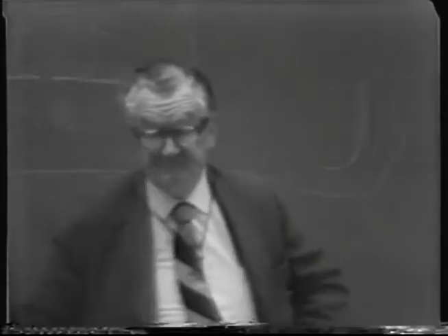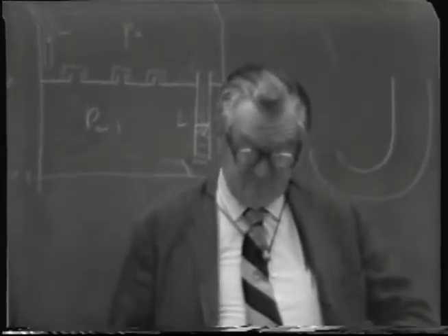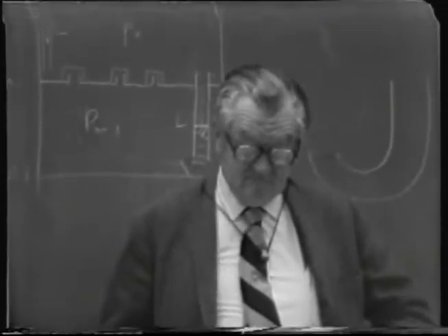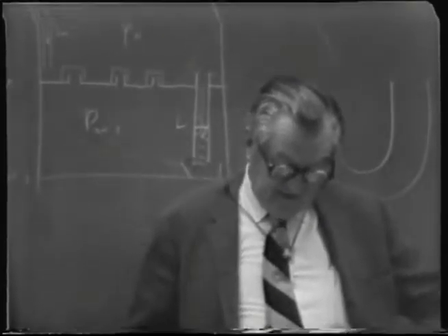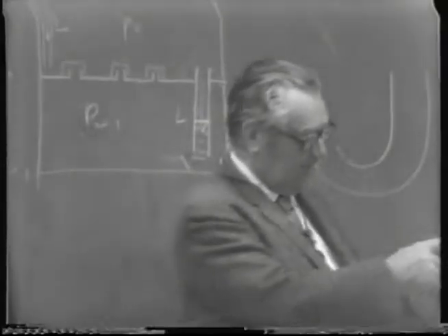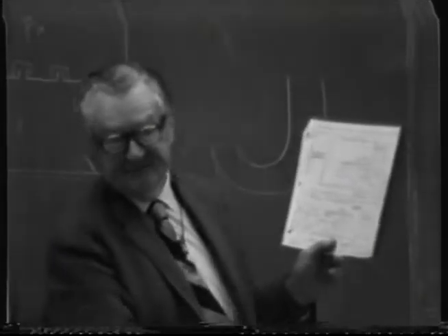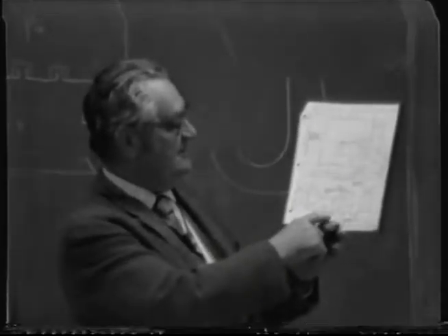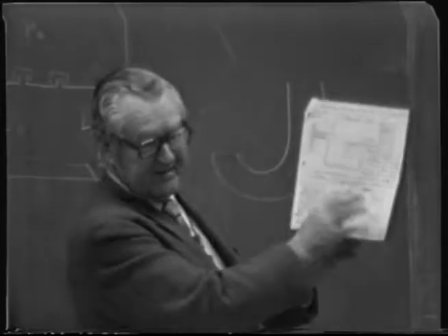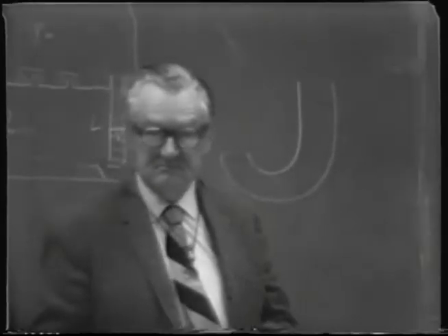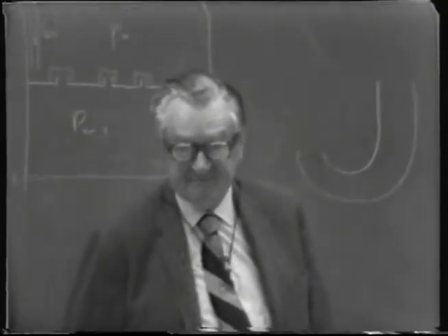A little bit. Now the steam that's going in to heat the column, this is liquid coming in from the feed, plus vapor that's being flashed up. So what's being sucked up in that vapor compressor is a combination of liquid and vapor? Actually, about the only action of the vapor recompression here is to provide a partial vacuum, and no vapor passes on up. Nothing is taken up. Well, maybe a little bit, but in fact, if it's operating the way it's designed, the vapor flashed off the stillage mixes with the feed directly and is condensed. But this chamber does operate under a partial vacuum, you see, in order for it to function in that fashion.